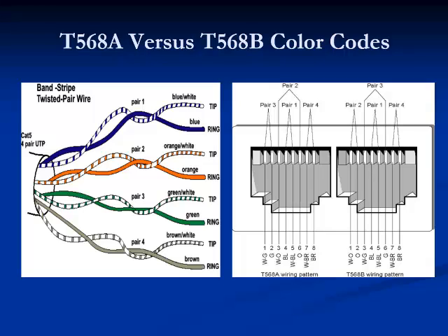The information outlets wired for UTP should follow one of 2 conventions for wire pin assignments or wiring patterns. These are T568A or T568B. They are nearly identical except that pairs 2 and 3 are interchanged.